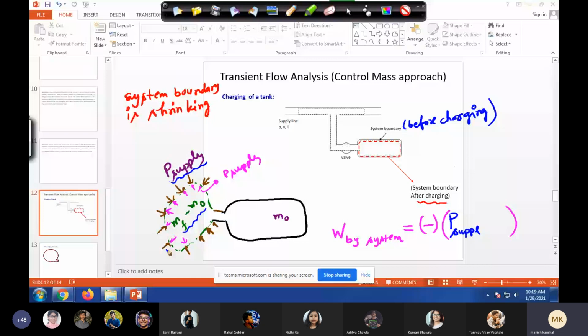So what we are doing with this MF minus M naught? It had some volume and we are making it 0, isn't it? You have to think this way, that this MF minus M naught is getting compressed and we will make this green boundary volume 0 finally, if everything goes into this tank. Because if this mass gets accommodated in this tank, the volume is not changing. See, you can write it this way.